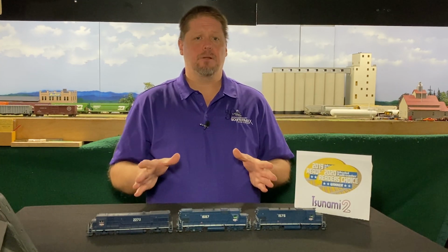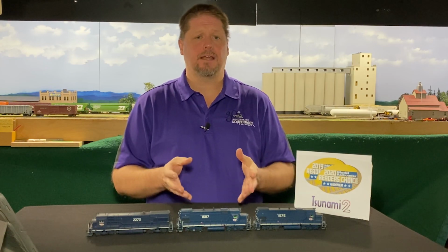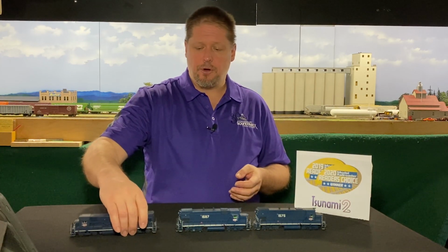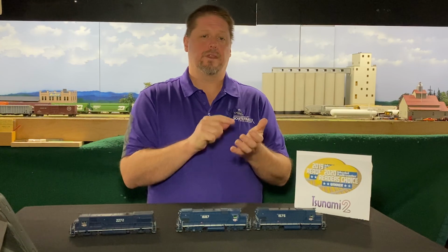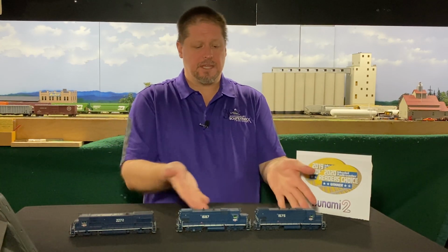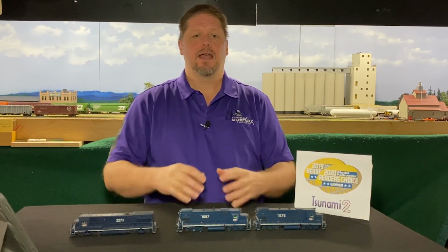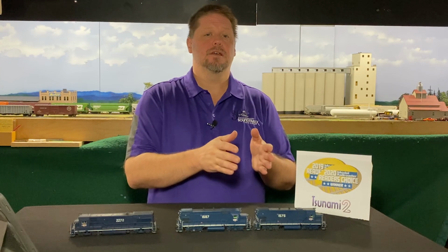to address 20. The best part about this is when you get into a club environment with those same 5 to 10 guys operating trains, that's only 5 or 10 DCC commands that are operating. Whether they're running a single locomotive by itself or a consist of locomotives, they still only have that one address. Then, when they're done with their throttle, they put it away, somebody else can come in and with the exact same road numbers in their train, they can put it on the track and everything will run just fine because